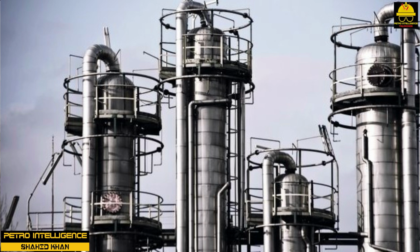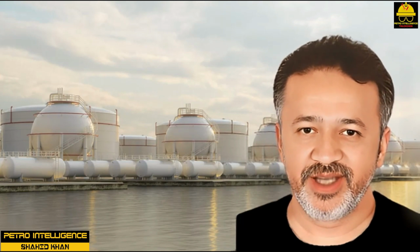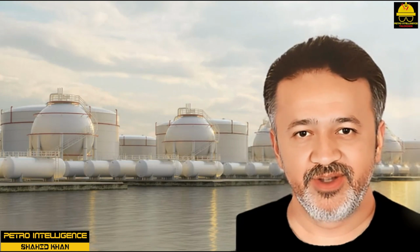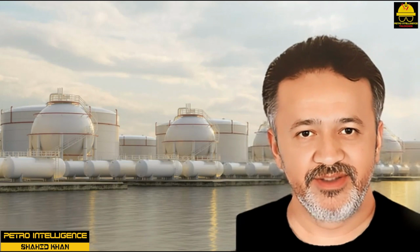There are many alloys of aluminum, which contain small amounts of other metals that greatly increase its room temperature strength. This strength in most aluminum alloys decreases rapidly with increasing temperature. Aluminum coatings over iron-based alloys have been used rather extensively in recent years to protect equipment from high-temperature sulfur and hydrogen sulfide corrosion as well as high-temperature oxidation.